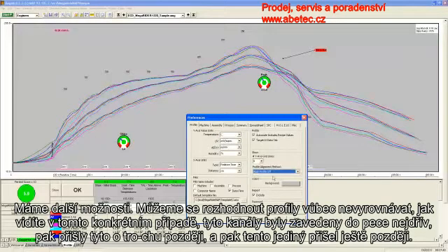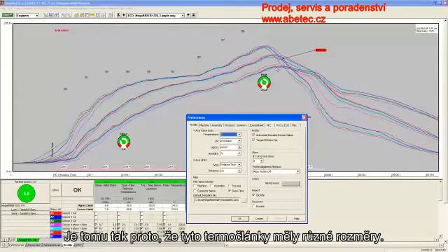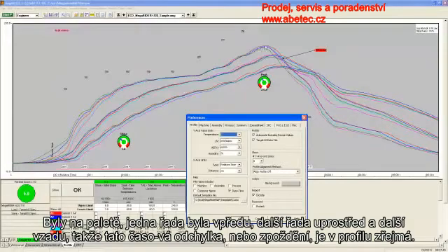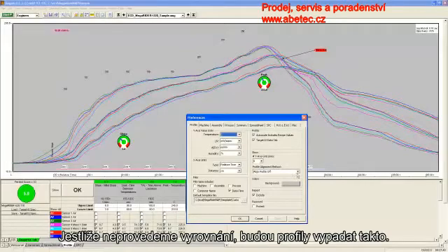We have other options. We can choose not to align the profiles at all, and you can see in this particular case, these channels entered the oven early, and then these came a little later, and then this one came even a little later after that, and that's because these thermocouples were physically, dimensionally different. They were on a pallet, and we had a row of them in the front, a row in the middle, and a row in the back. And so this time offset or lag, as you can see, is apparent in the profile. And if we didn't align, that's what the profiles would look like.